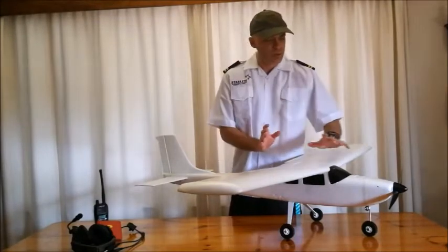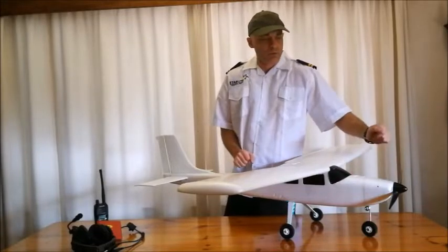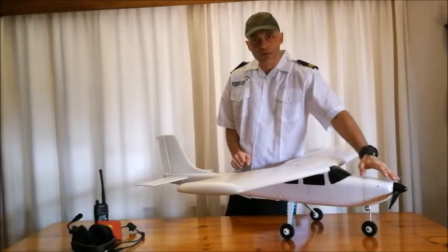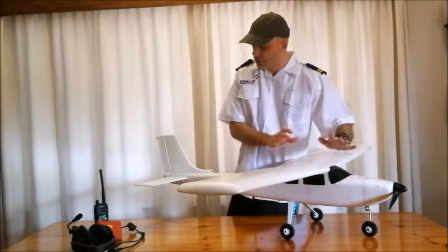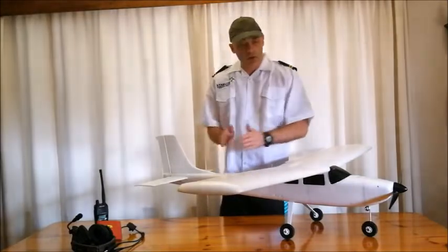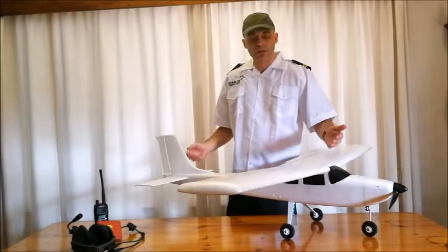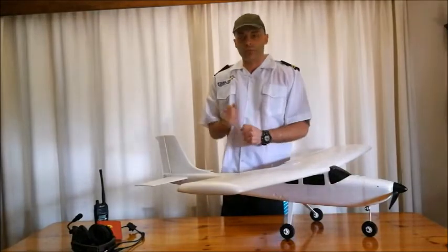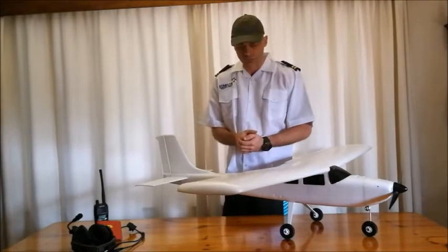Yet if you can have the weight towards the front of the aircraft, like you'll often find the engines are in the front of the aircraft, a lot of the luggage or people might be sitting towards the front of the aircraft, then that will cause it to have a longer arm length, and therefore there would be a larger moment. So there's less input that the pilot would have to give to control these surfaces.